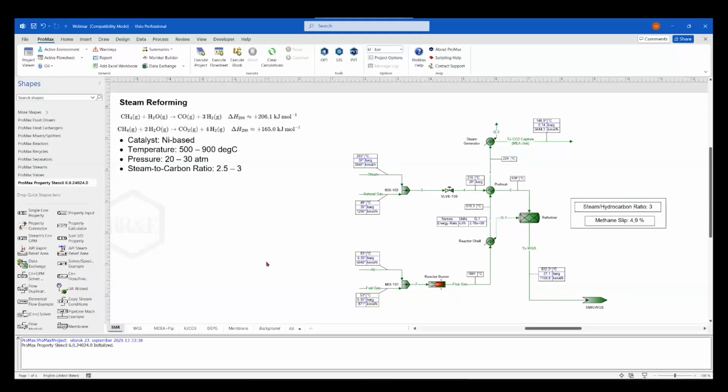In this technology, the catalyst is also sensitive to H2S, so any significant sulfur in the natural gas must be removed in a desulfurization unit before the SMR. And if the feed contains ethane or heavier hydrocarbons, a pre-reformer can be installed upstream of the main reformer.